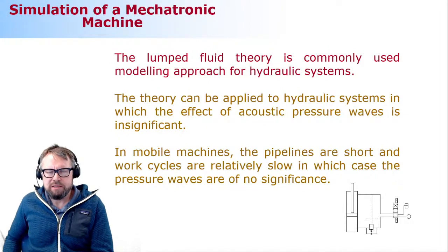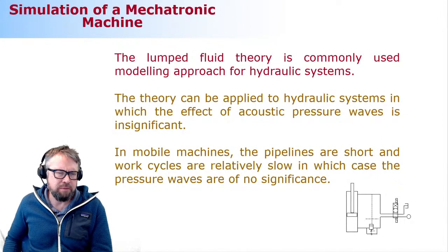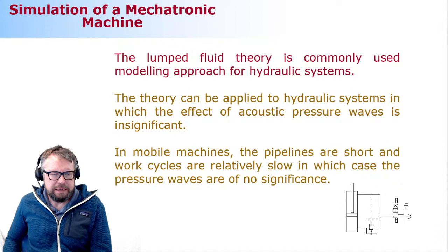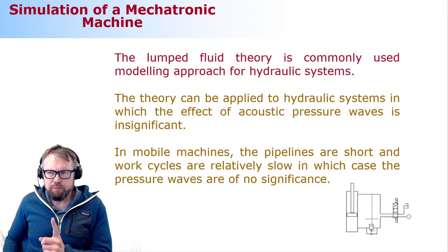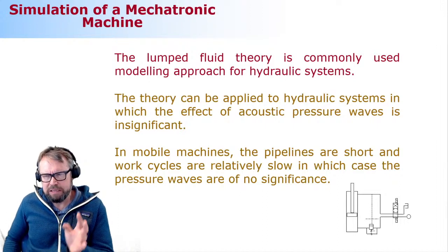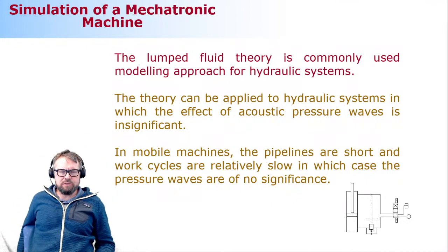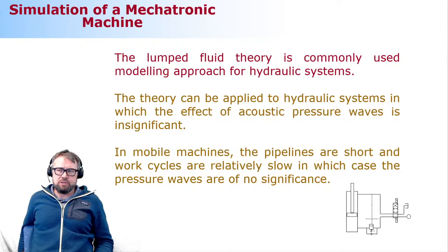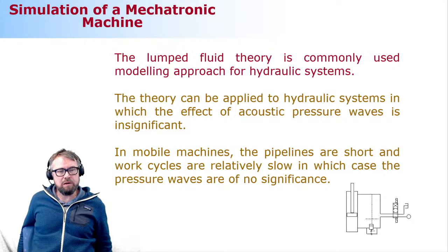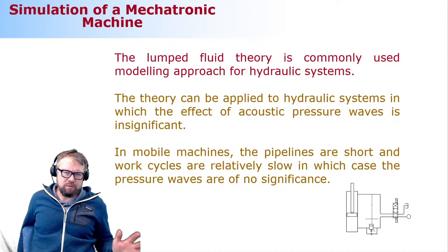So this method based on lumped fluid theory cannot take the acoustic pressure waves into account, because we compute the pressure only at one location within one volume. The pressure waves traveling back and forth are the ones we cannot take into account, which is a drawback in certain applications.